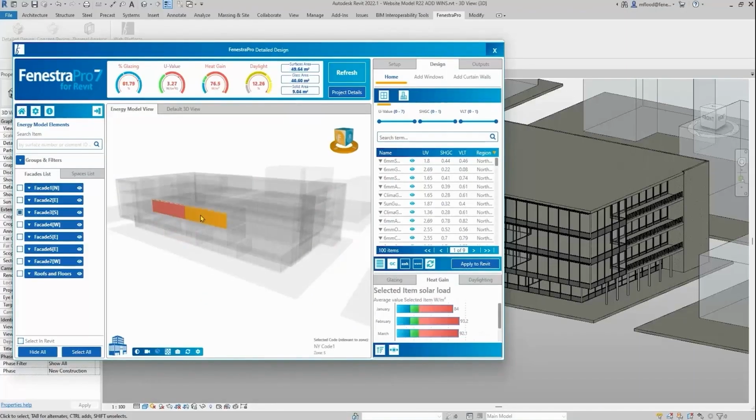But then also, that's generating the geometry, but we also want to generate the materiality. So again, from a database of quite a lot of manufacturers' products and IGUs that are off the shelf, we can start searching for the appropriate glazing solution. So Guardian Glass, Vitro Glass, Viracon in the United States, Pilkington. You can start dialing in performances that you're trying to achieve.